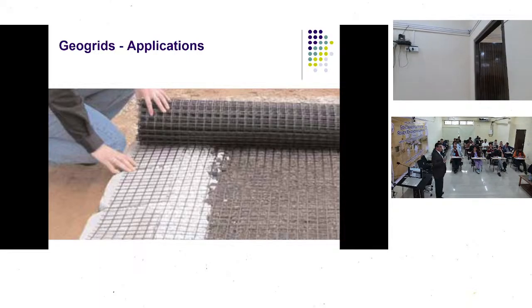Basically, if I talk about a slope, have you been exposed to some slope stability analysis? Slope stability, slip circle. Do you remember? Okay. What is a slip circle? Slip circle means suppose we have a certain slope. In case there is a failure, it will be in the form of a curve. This is how we define it. Suppose this is the slope face, so maybe it will be sliding like this. We say it may be like an ice cream scoop. So that will be the slip surface.